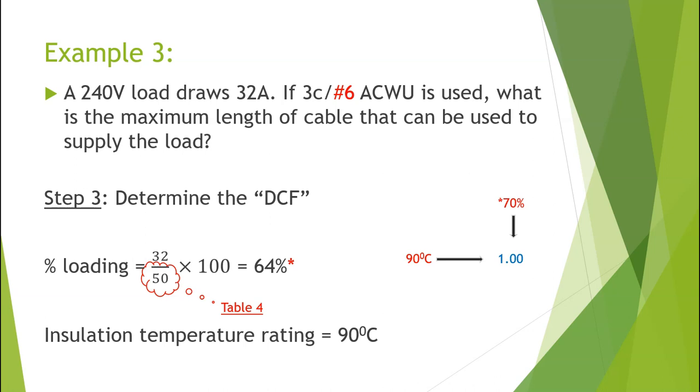However, the reality is that the conductor we are running is in fact aluminum. So when we do our calculation for a percentage loading, we need to do this based upon the actual conductor that we are running, not the hypothetical conductor we used in table D3.